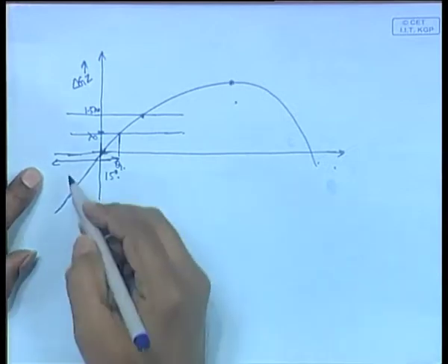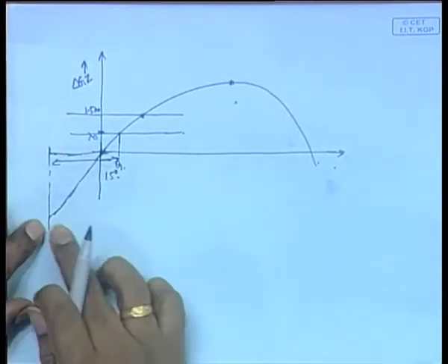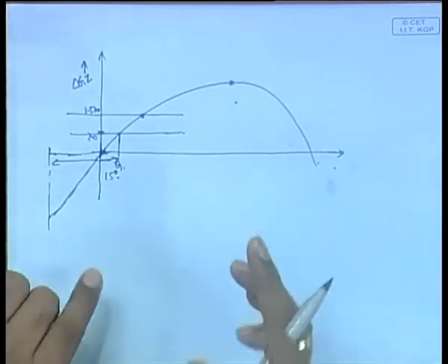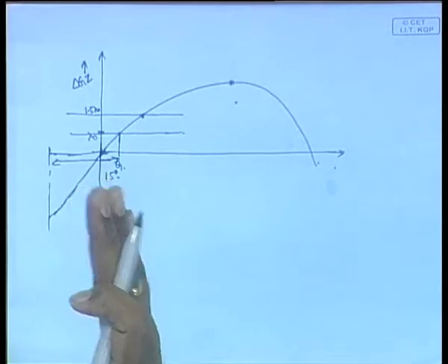So, the ship started from here, this was its worst condition and it heeled up to this theta 1. So, from here wind kept blowing and it heeled up to theta 1. In a way we found theta 1 and then we went back saying that it started 15 degrees before. We do not know what that initial position is, that is why they have said assume the ship is in the worst condition, this is the worst condition.